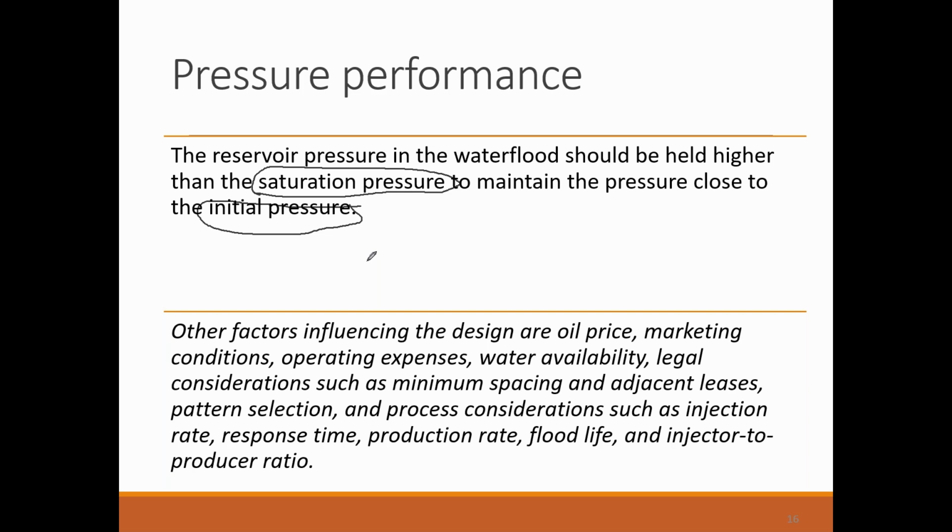In absence of PVT properties taken on an oil and gas sample, we may not know the saturation pressure, which is also known as the bubble point pressure. But you should keep in mind that the pressure should not be declining much. If it is declining much, definitely the lifting capability of the reservoir by virtue of its own energy will be reducing.